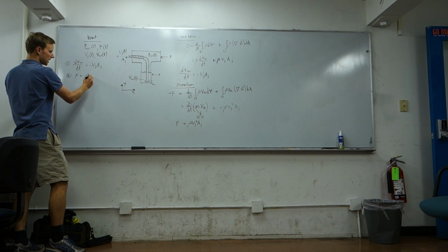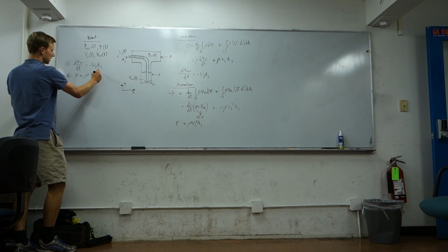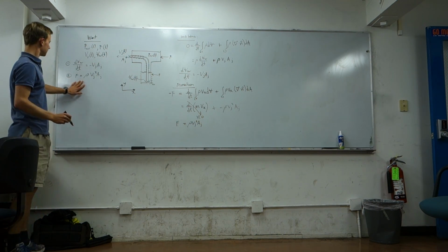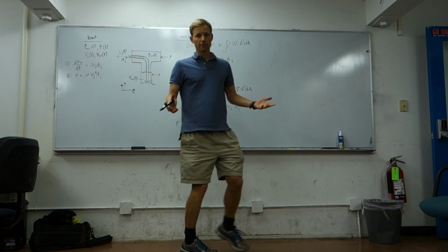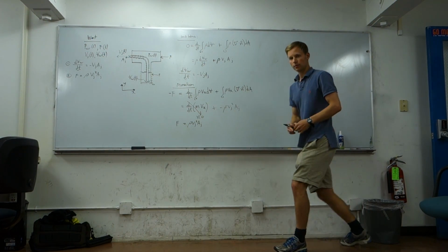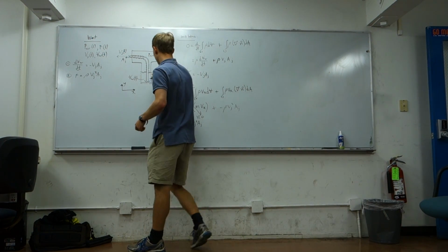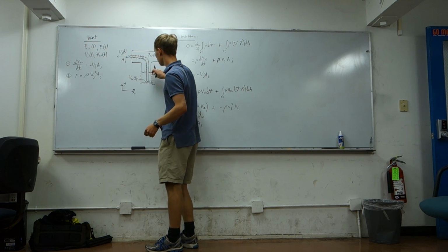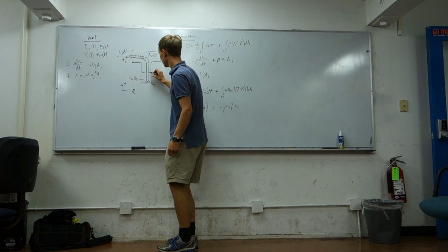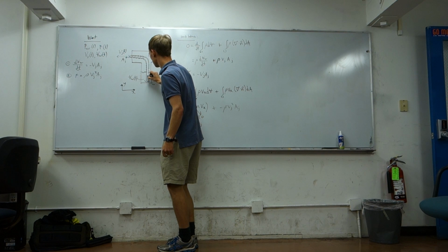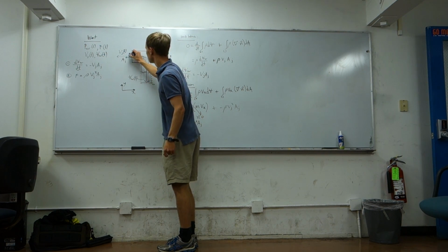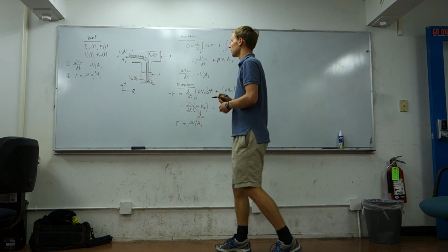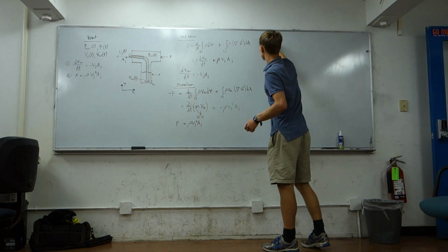So we know we're going to need another expression for Vj in order to evaluate force. So what can we use for the Vj term? Well, we'll use Bernoulli's equation, which relates the energy along a streamline. So we'll start at state 1, which is the free surface of the water. We can draw a streamline that goes all the way up through the dip tube out to point 2, which is our atmospheric point. So Bernoulli's